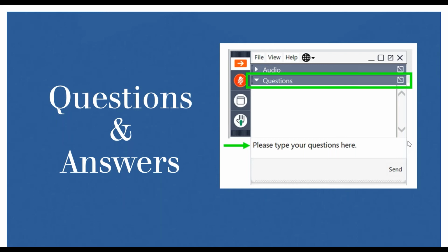So, thank you, Mr. Yu, for answering this. There's also one thing that I forgot to mention. The number of strokes is indicated on the tubes. If you look at the tubes, there will be an N, and beside the N there will be a number. This is where you see the number of strokes required for the tube itself.